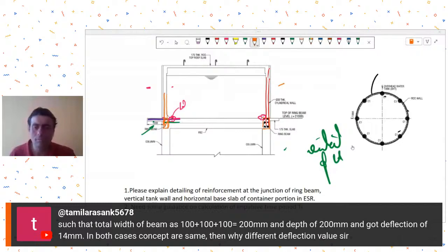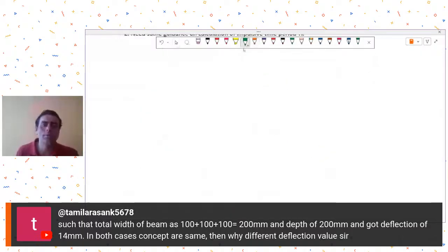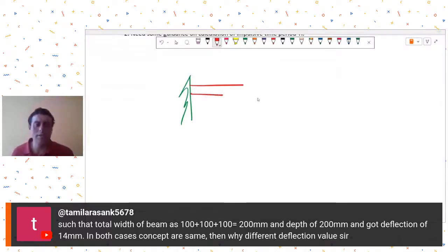No, no. So you must have made some mistake in assignment. Remember, if you are bringing it from the section wizard to STAAD, there is a possible problem with the section modulus values, because it gets interchanged sometimes. So first of all, ensure that you have properly taken the section wizard values and brought them to STAAD.